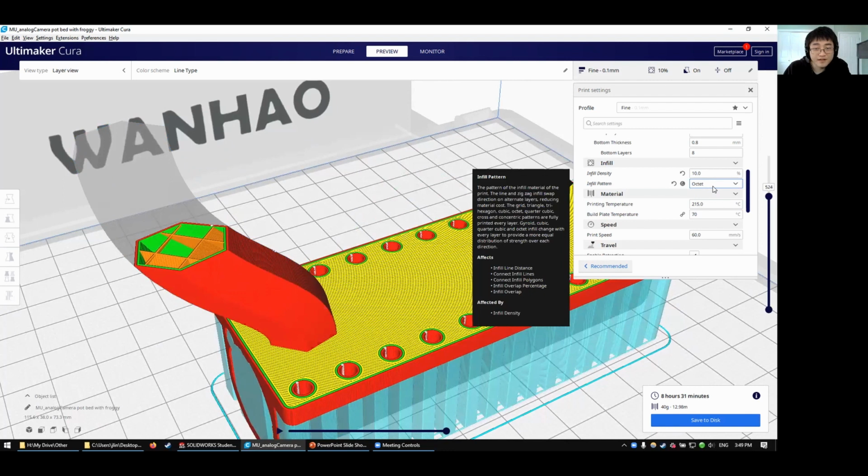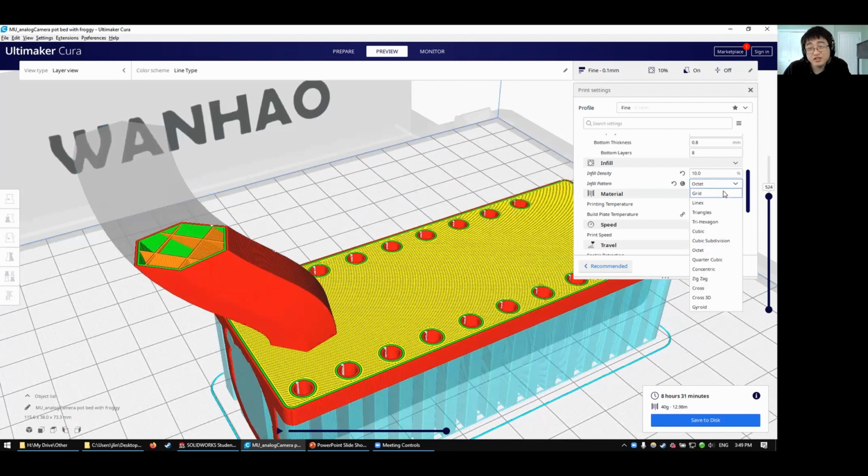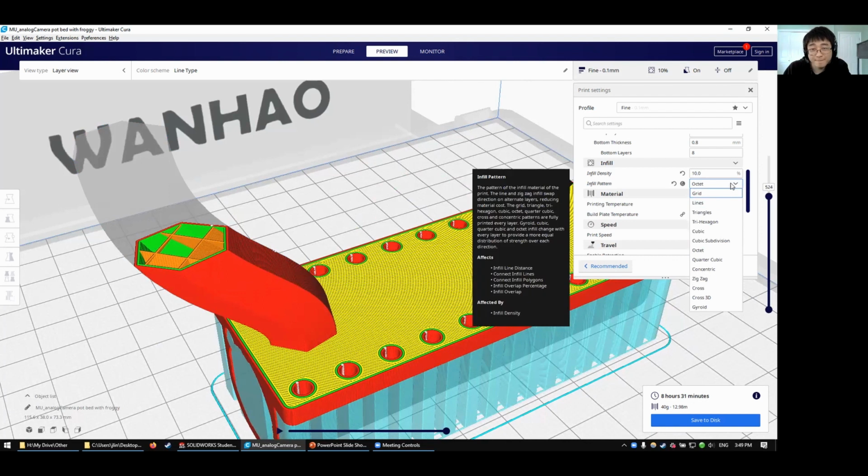About the infill stuff, that's a good point, Daniel. I'm not very sure myself of the relative strengths between each one. If we're going to print 100% infill, then I suppose the pattern you make doesn't super matter. One thing I'd recommend is to not use grid or lines for anything that you need to actually be strong.